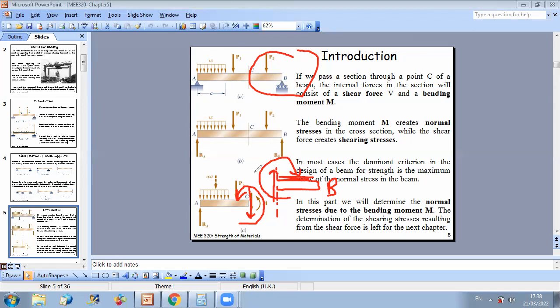To consider a shear force positive, it should always rotate clockwise with respect to the end of the beam. And for the bending moment to be considered positive, it should compress the upper part. So when you study right parts, you use these directions. When you study left parts, you use these ones. This is done to unify the sign, if you want.